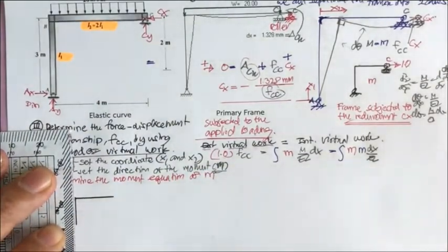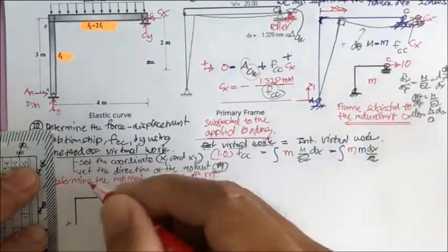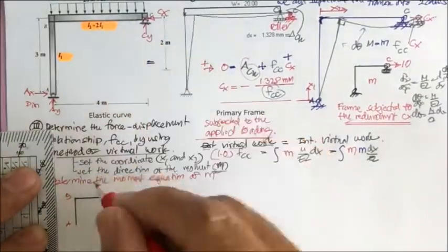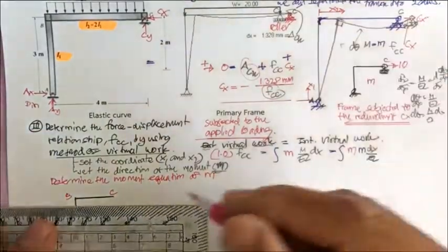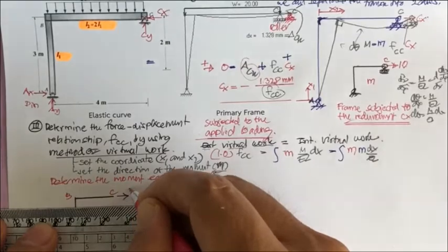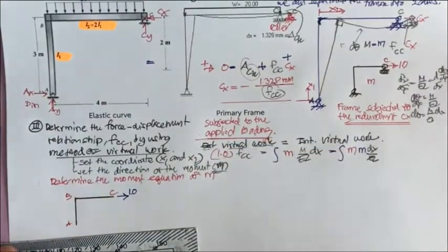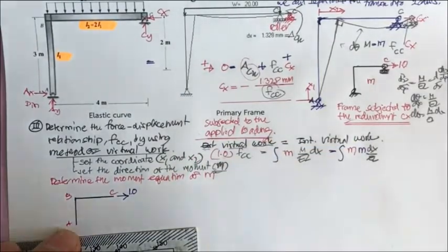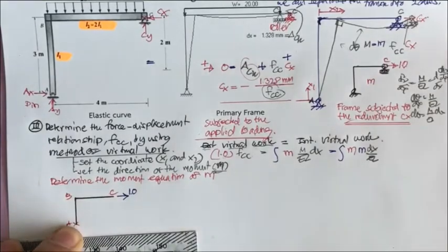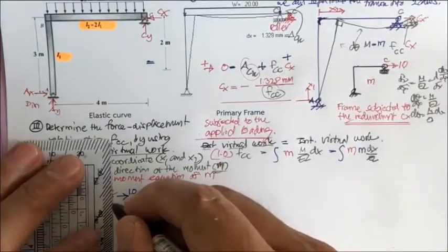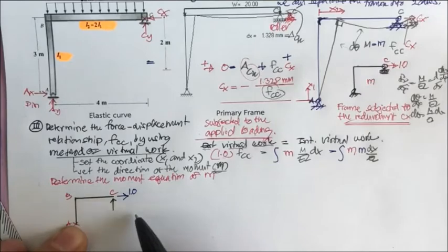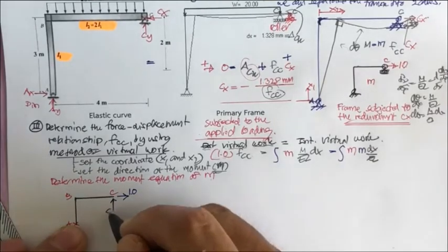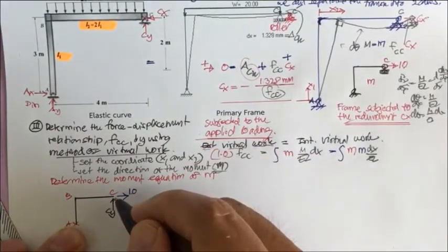These are going to be points A, B, and C. This one is subjected to the force of 1.0. Now, if you take the moment here, you will see you have the reaction here in this direction. Since 1.0 is going to rotate clockwise, this C sub y is going to rotate counterclockwise.